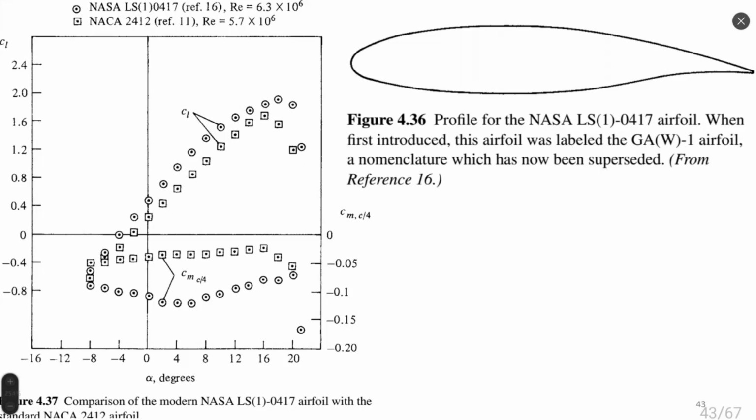It means that there is no one best airfoil for all applications. Maybe some airfoil is better from one point of view for one Reynolds number or one Mach number of flight. Another airfoil will be better for another Mach number of flight. This is why there are hundreds, maybe already thousands of different airfoils, and modern airfoils are still being elaborated because of this reason.